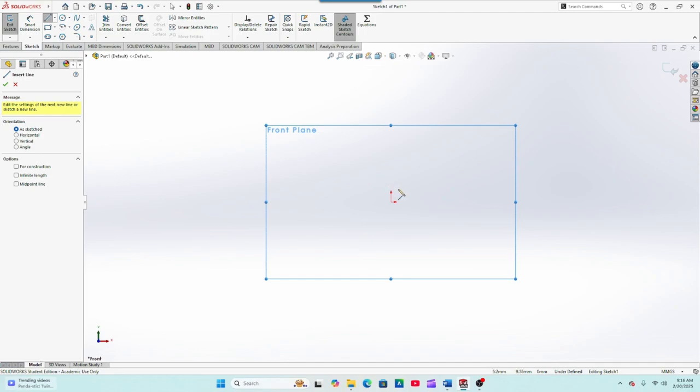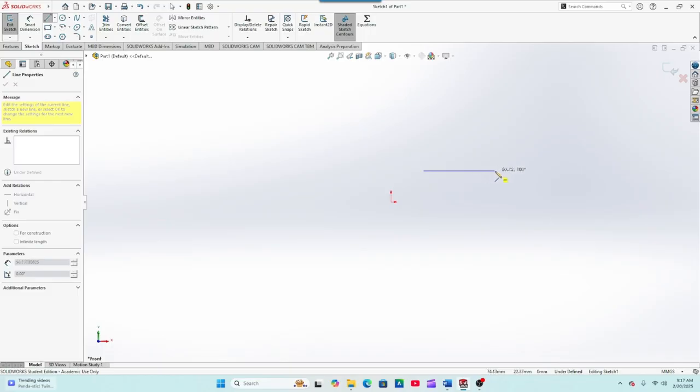Now, when we draw or sketch in SolidWorks, a few things that we need to remember: everything that we do needs to have either a dimension or a relation or both in order for a sketch to become fully defined. As an example, I'm just going to freehand sketch out here, out in the middle of nowhere, and draw randomly a few lines just to show you some stuff and close some stuff out here.